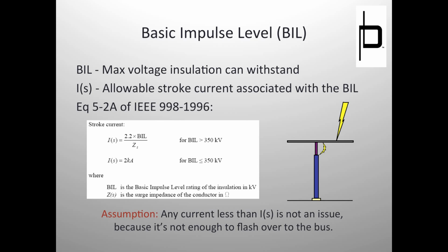Now, will it cause some minor issues with the electronics? Maybe that's possible, but for the most part the equipment can absorb it, and that's why we put those 900 kV insulators. And let me state this: when somebody says 900 kV BIL, basic impulse level of that insulator, does that mean that 100% of the time a 900 kV or less amount of voltage will not cause flashover?